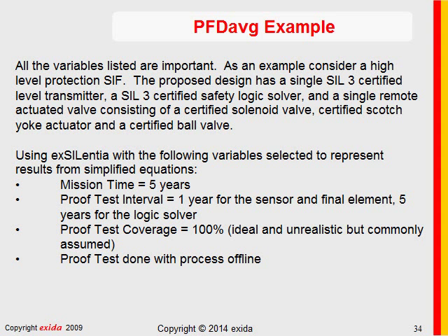We've also estimated rough proof test coverages and published them in several of our books. I know that our final element book has a full table of proof test coverages, and the Blue ISA book has a table of proof test coverages as a function of instrument types, primarily solenoids, actuators, and various types of valves. So, and there is a whole web seminar on that, but that's just the short answer. Another one.